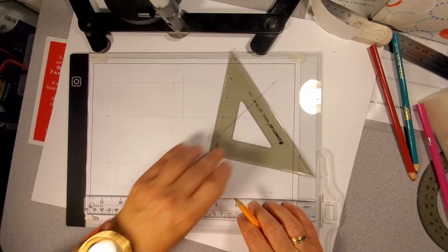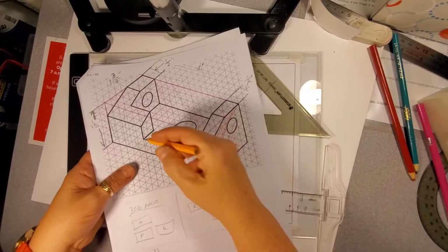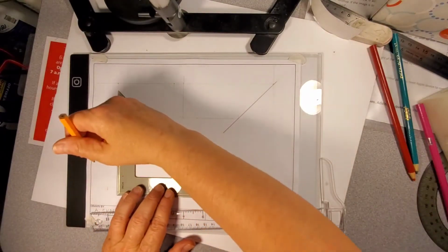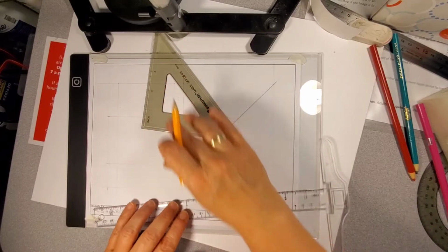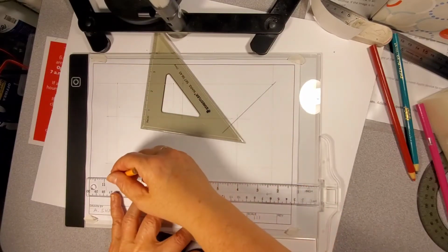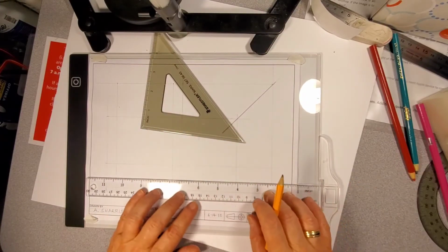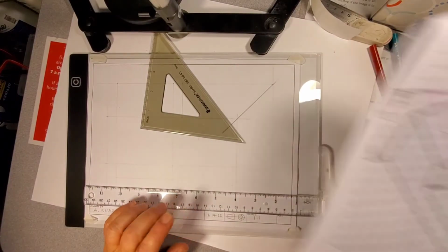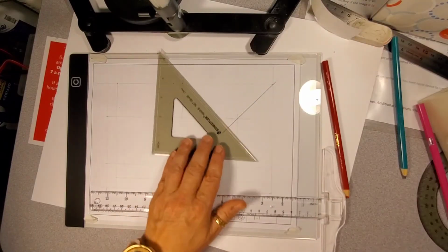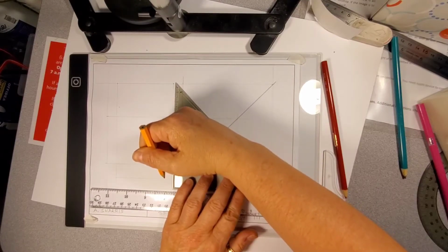Now, in the front view, you see that this thing goes up 2 squares, which is 1/2 inch. So you know you can measure 1/2 inch up. So you know the bottom of this thing here goes across, and then you have it also on this side. Now you see this goes up 2, so a quantity of 2. So this thing goes another 1/2 inch up.